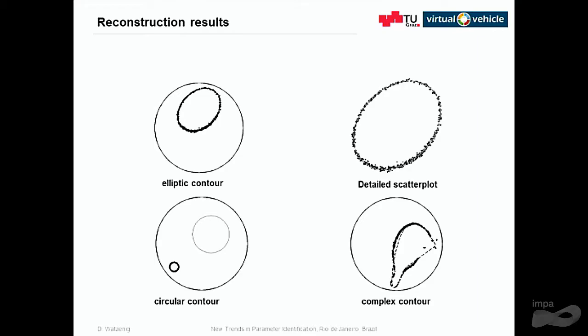Because, as a measurement engineer, as a signal processing engineer, I usually like to say, whenever you have measurements, you have statistics. Measurement is always like statistics, and once you have statistics, you have to deal with stochastic processes, and that means there is not only one single solution, there's always a range of feasible solutions, given or predefined due to the stochastic process driven by the measurements. And the smaller the variance, the better, of course, is our estimator, our reconstruction result.